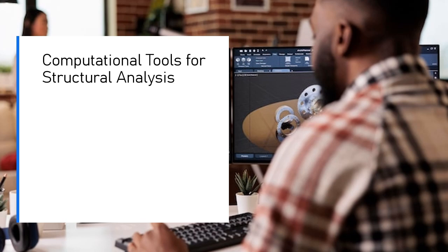Challenges: the design team faced the challenges of wind load, seismic loads, and lateral forces from the extreme height and location in an earthquake-prone region. Solution: ETABS was used to model the building's structure, taking into account the complex interaction of wind pressures, dynamic loads, and vibration modes. ETABS was employed to simulate how the building would respond to earthquake forces and wind-induced sway to ensure the structure could withstand such loads without compromising safety or comfort.